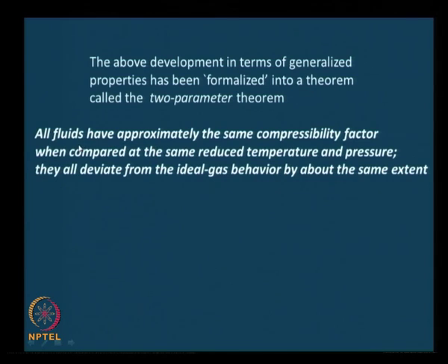This is essentially saying the same thing that we have mentioned earlier, but this brings in another perspective. Let us read the first sentence again to understand this perspective. All fluids have approximately the same compressibility factor when compared at the same reduced temperature and reduced pressure, and from this, just by using the reduced temperature and reduced pressure appropriately and using the compressibility factor, we have information about a large variety of gases. That is the advantage here.